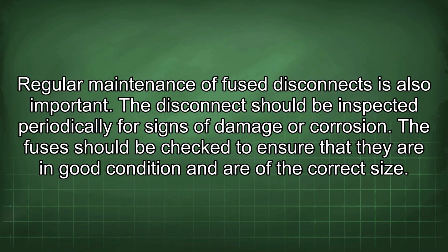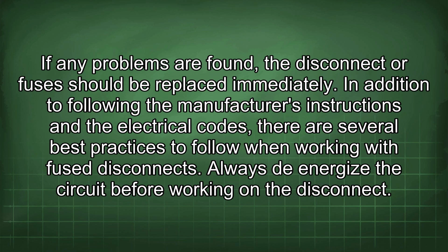Regular maintenance of fuse disconnects is also important. The disconnect should be inspected periodically for signs of damage or corrosion. The fuses should be checked to ensure that they are in good condition and are of the correct size. If any problems are found, a disconnect or fuses should be replaced immediately.